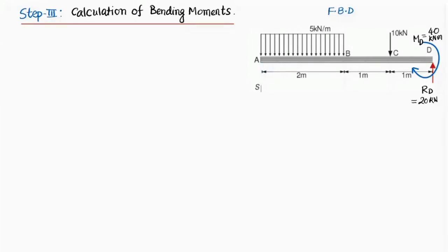There is a sign convention we are going to follow. So let me explain the sign convention for bending moment, friends. If due to application of various forces or moments, your beam is bending in this way, this is called sagging of the beam. This kind of bending moment is taken as positive, friends. This is called positive bending moment.